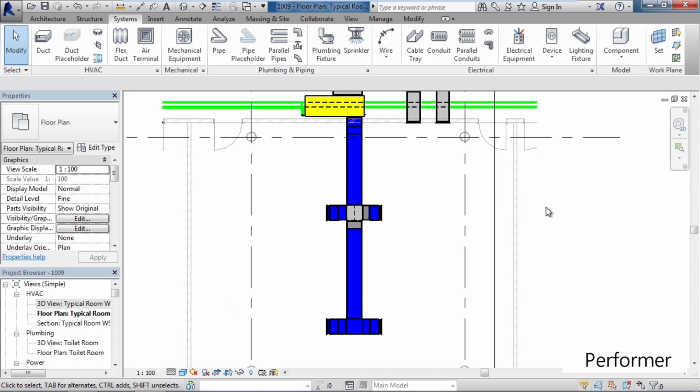And then to actually use the automated method of creating ductwork, we selected all 5 of those elements. With all 5 elements selected, we chose the placeholder command to create actual placeholder layouts of this actual duct work. Now again, we draw placeholder lines originally, but then it interpreted those into the actual duct work themselves.